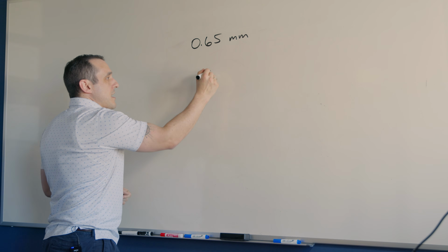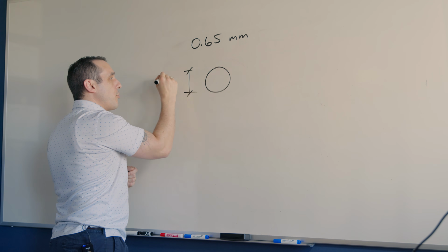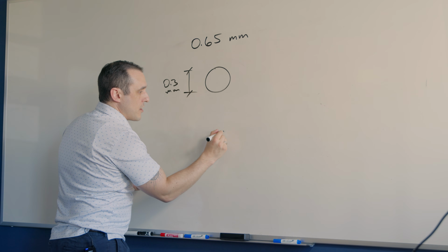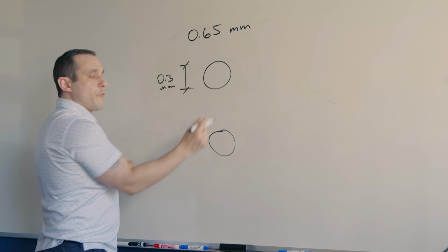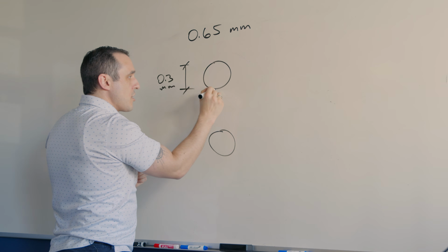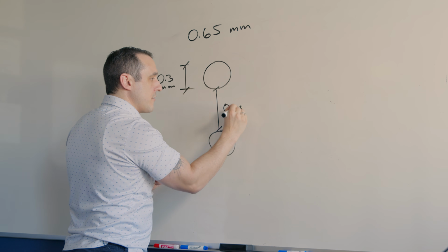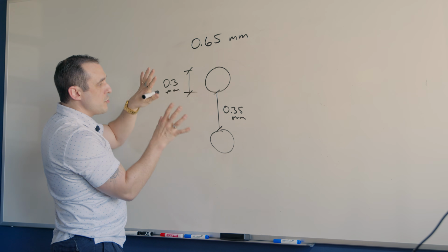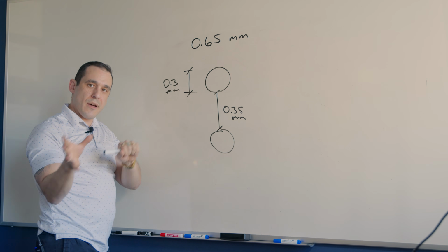So in this pad pitch, our pad size is going to be, for example, 0.3 millimeters. So that's our pad diameter. And then we're going to have another pad down here, which is also 0.3 millimeters. Now, if we just calculate the edge-to-edge clearance between these two pads, we're going to pretty quickly see that this distance here is 0.35 millimeters. Now, these numbers are really important because if I want to use mechanically drilled vias in these pads, what am I going to have to do?